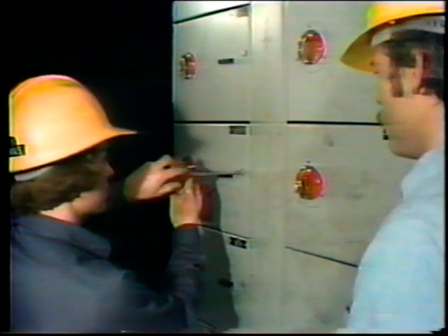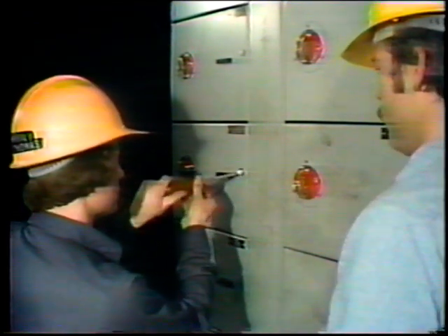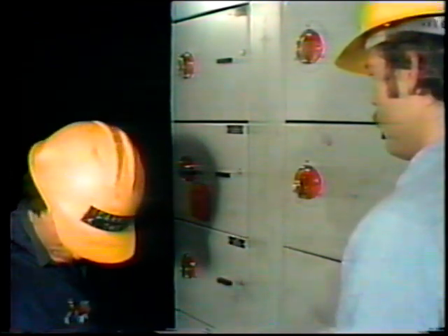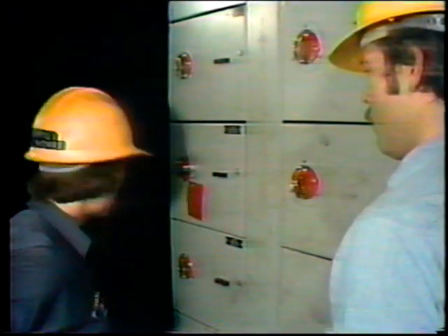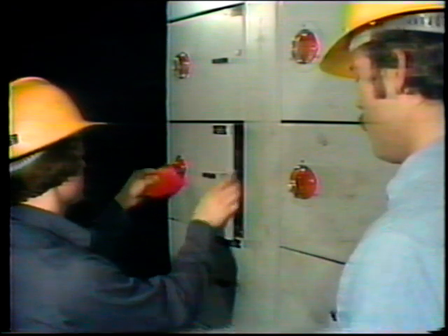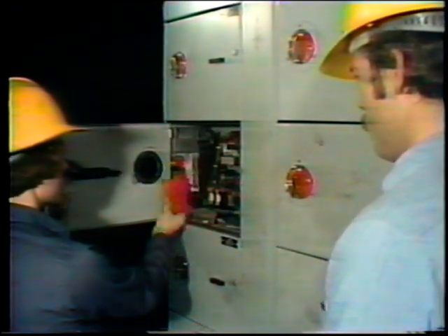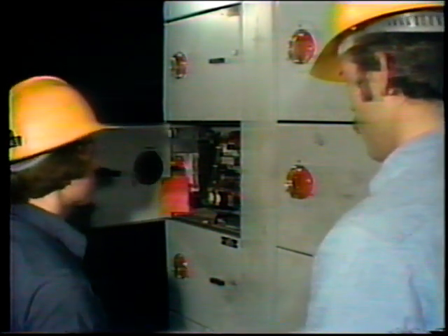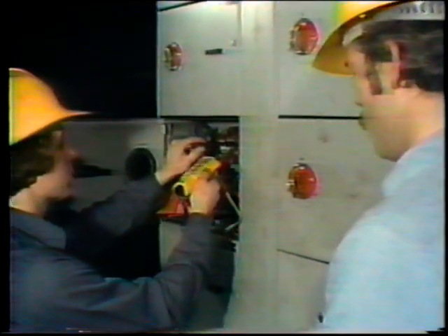The controller is turned off and tagged in the off position. Before the electrician begins his testing for grounds and shorts, he first checks the controller to make sure that it is completely de-energized. When testing a controller to see if it is de-energized, voltage on all phases and all phases to ground are tested. The instrument he uses to test if the controller is de-energized is a voltage tester.